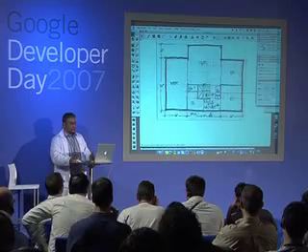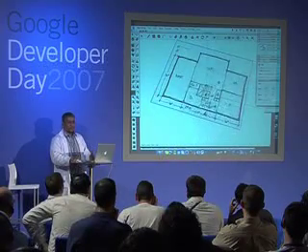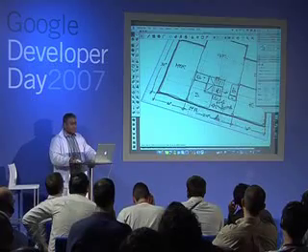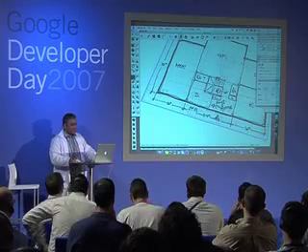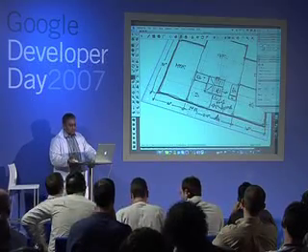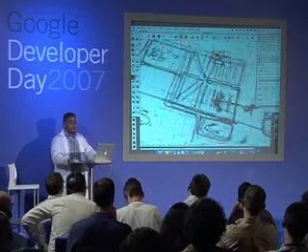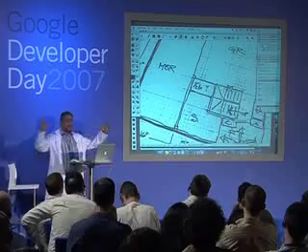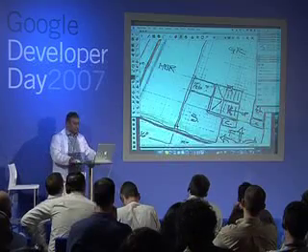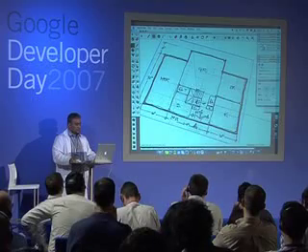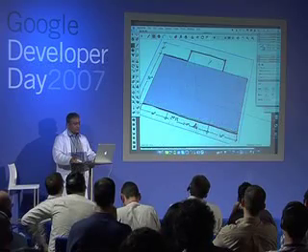And I can bring it in. Here's my image. Okay. If I know a distance, I can scale this up. So I can say from here to here is actually 25 meters. So now I have an image which is roughly 1-to-1 in its size. And then just use it to draw. So I'm going to draw that.